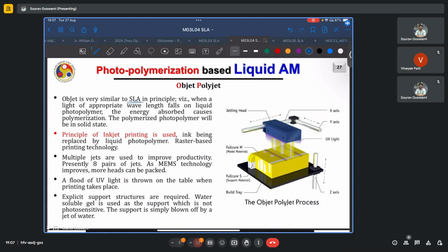A principle similar to inkjet printing is used. We just extend it to 3 dimensions. But where the difference lies is that here you have support structures made out of a different material compared to the build material. Whereas in SLA, it was not really possible as the vat was filled with resin of only one material. Now, based on the printing strategy or the density or the amount of, say, input power, we could selectively make the support structures weaker than the built material itself,